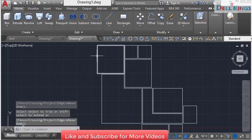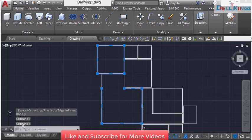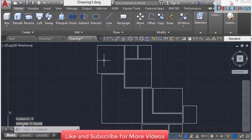So now we are going to select these outer rectangles and explode them so that we can now create our outer wall. So select all of these outer rectangles and type X for explode and press enter. So now you have all of these lines separate.